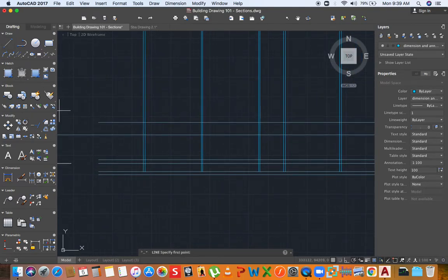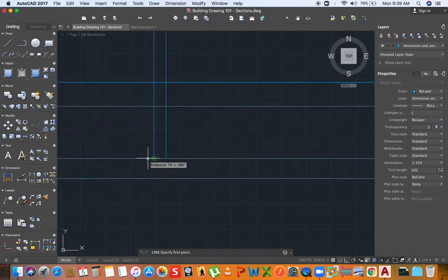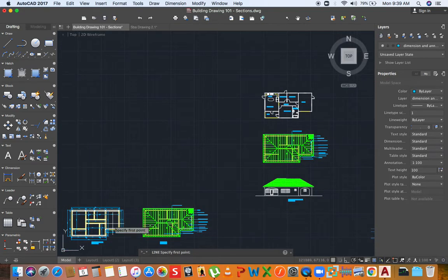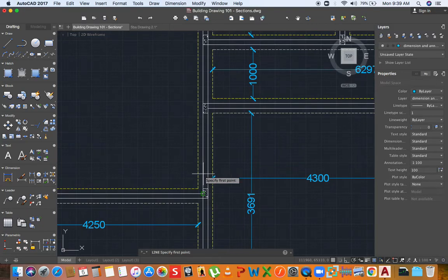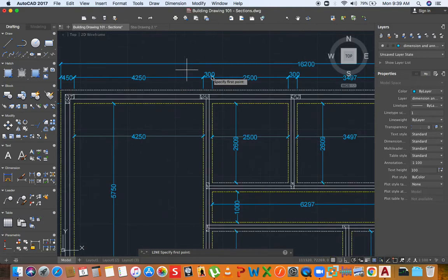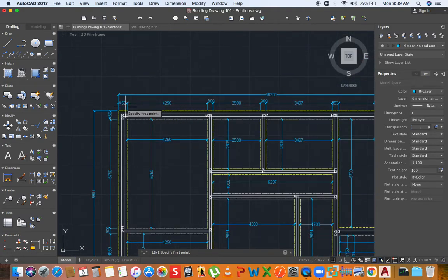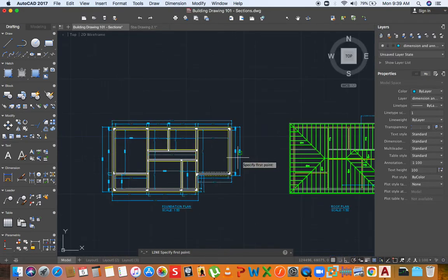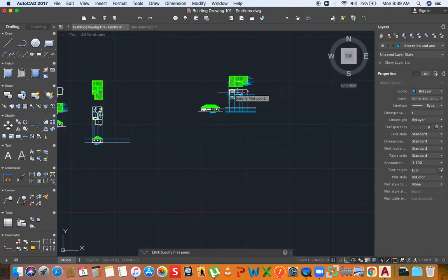I'm going to measure 150. Well, this now depends on the foundation drawing that I have. Let me see how far I offset these things. So the internal walls are offset 100, the external walls are offset 150. You see the internal trench, this is the thickness of the foundation footing for the inside wall. The width of the outside wall is 450. So 300 and 450. So this was, let me go back to it.